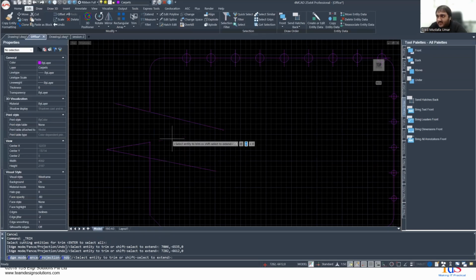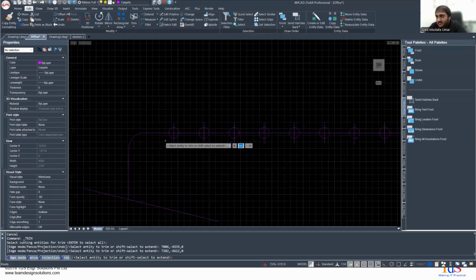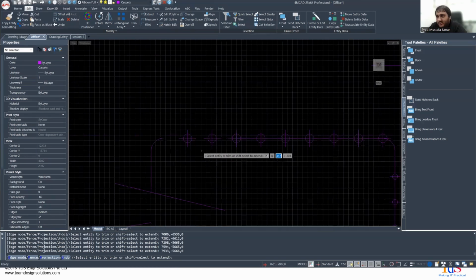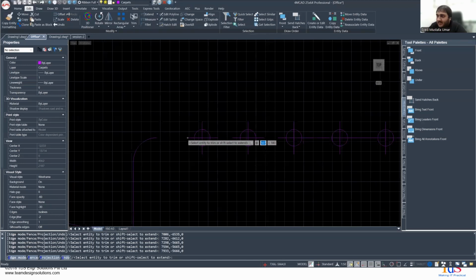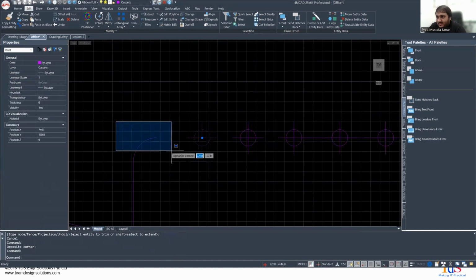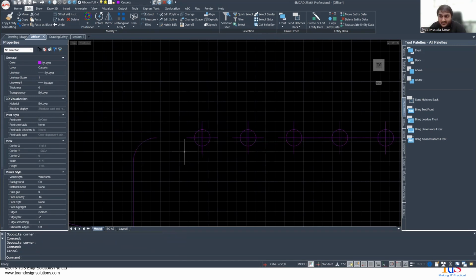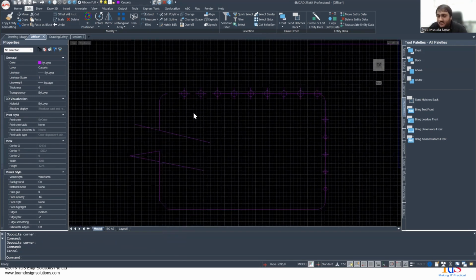Over here, it will delete this because this was the first point of intersection in this direction, and then this was the first point of intersection in this direction. And I can do this for anything, essentially, where it's removing all of these lines with reference to whatever entity it first intersects with. So right now it intersects with this entire point as well as this filleted corner. Hence it removes that portion altogether.